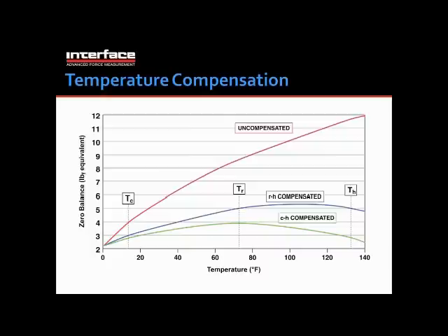The second case, the blue line, is a load cell that has been compensated. However, the compensation took place between temperatures that go from room temperature up to a hot temperature. And we can see that the error has been minimized. However, we still have just over 5 pounds of error induced in our measurement because we have not done a compensating procedure that goes from a cold to a hot temperature.